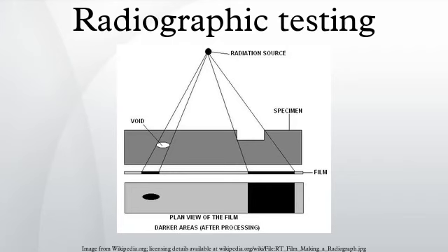Radiographic testing, or industrial radiography, is a non-destructive testing method of inspecting materials for hidden flaws by using the ability of short-wavelength electromagnetic radiation to penetrate various materials. Either an X-ray machine or a radioactive source, like Ir-192, Co-60, or in rarer cases Cs-137, is used, or an X-ray computed tomography machine, as a source of photons.